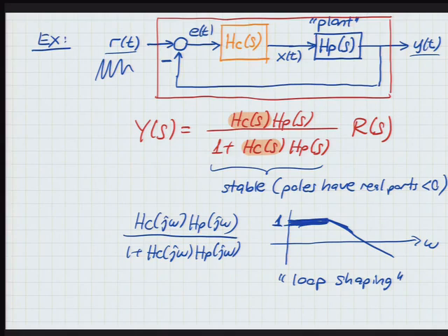So typically people will say, well, I want my frequency response to be close to 1 in this range, and then I want it to drop after a certain frequency range because that's where noise starts becoming dominant. Okay? All right, so we'll probably not talk about loop shaping, but at least we'll learn how to manipulate transfer functions and how to evaluate stability of the feedback and things of that sort. Right? And move on.